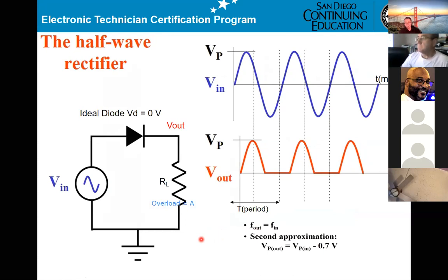When you remove the board from the system to test, we normally deal with electronics, so the capacitors don't need to be discharged. Only if you're working on a TV or very big circuitry, then you have to discharge it. No more voltage.